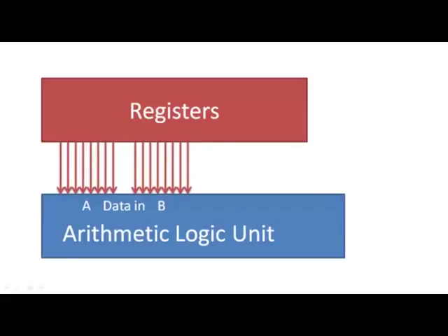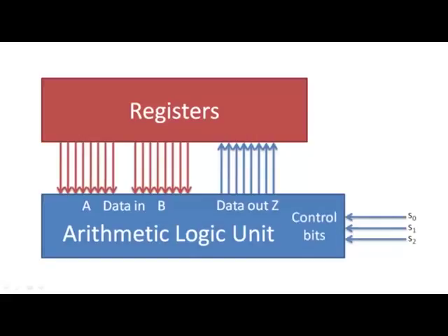The ALU will perform a calculation on these 2 values and send the result back to the register file to be stored. We tell the ALU what instruction to perform by sending it a set of control bits that encode a message of what operation to perform. Because the ALU is a combinational circuit, it will perform these calculations immediately.